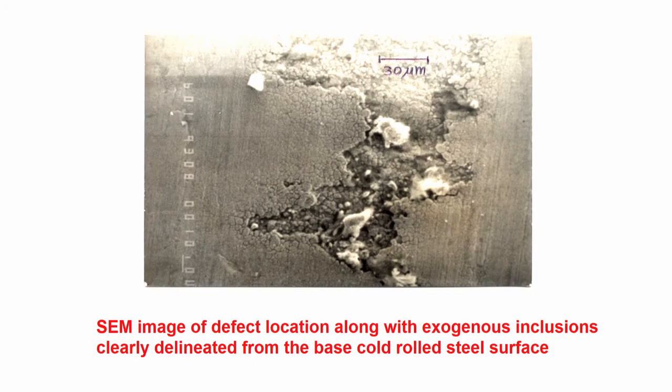Now, look at another defect, and this also has been seen under SEM, scanning electron microscope image. So, we find how the defect looks. It looks typical. I was telling you earlier, the surface lamination defect is a typical surface lamination problem, as if the surface has got torn. The defect area is a jagged sort of surface, and on that you find a lot of inclusions.